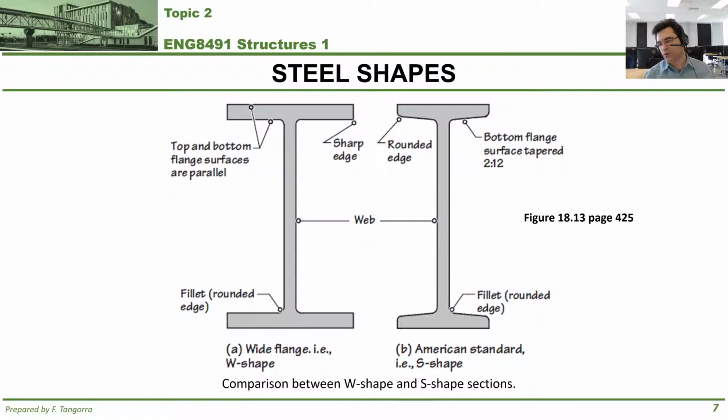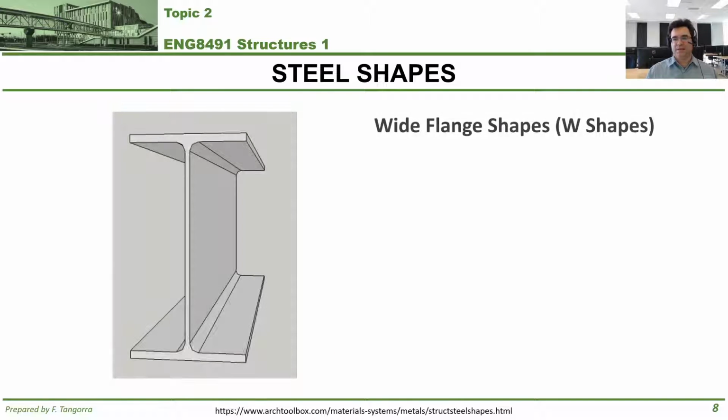The shape on the right, an S shape, you'll notice that its edges are more curved and gradual, and the flanges at the top are narrower. So usually these might be used as joist members or secondary structural members. So a whole bunch of these holding up a floor together, for example, with nothing else sitting on it other than the floor.